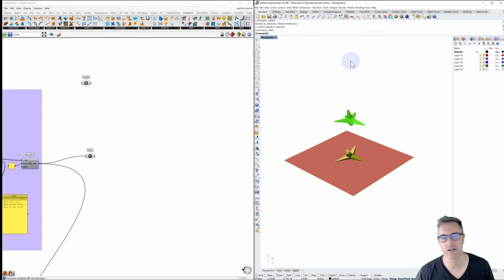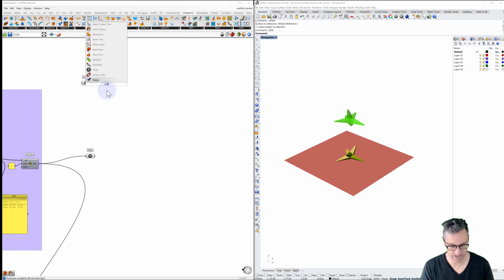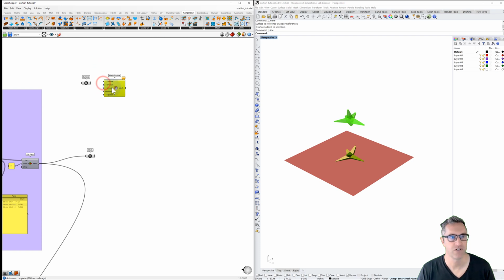And so let's create a mesh this time. Last time we just defaulted to a mesh. This time I want to be more specific, so let's create a mesh surface. And this is why we had to do this. You can see the surface comes in. Now we can hide our surface from our surface container. But we do want to set the U and the V components.